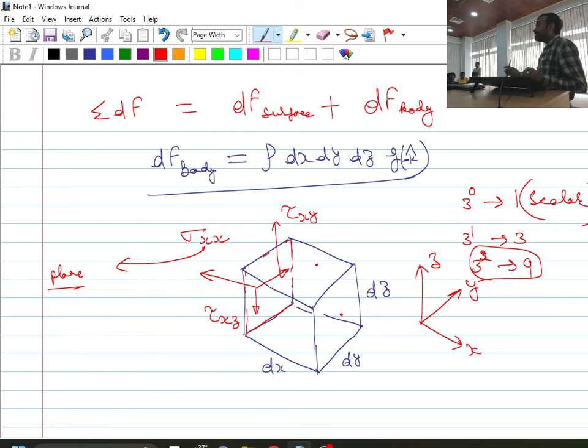Because if I say that a fluid element is at rest or in equilibrium, because we are talking about the fluid element in equilibrium, then whatever stresses are acting on the left face, the same magnitude will be there for the stresses acting on the opposite right face. So here also I must write, with the direction opposite, sigma xx, tau xz and tau xy. Fine. So is this point clear?